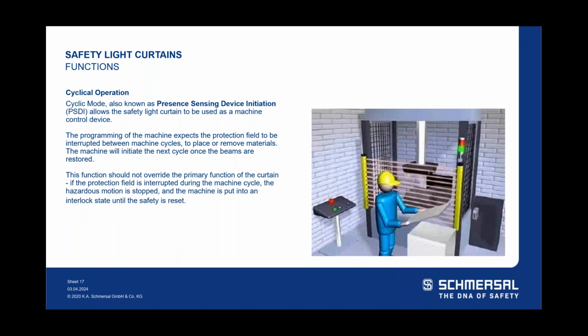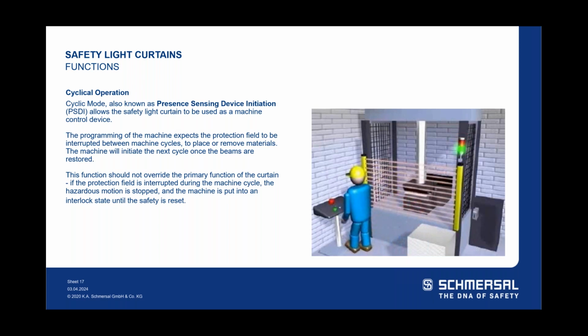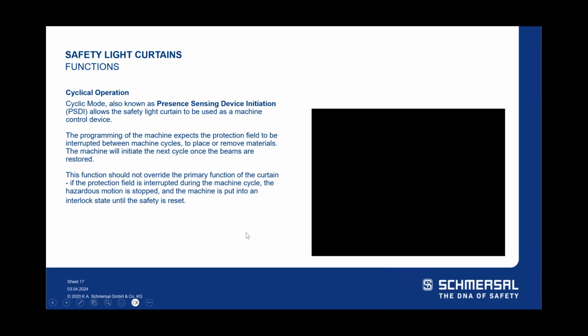Cyclical operation, also known as presence sensing device initiation, allows the light curtain to be used as a machine control device. The programming of the machine expects the protection field to be interrupted between machine cycles. Again, I have a video here, but the proper cycle, it's going to be fine. He's not putting his hands through there when that press is activated. If he tries to say, oh, I got to grab that, it's not going to allow. It'll stop the machine and it'll need to be restarted. Again, that's cyclical operation.